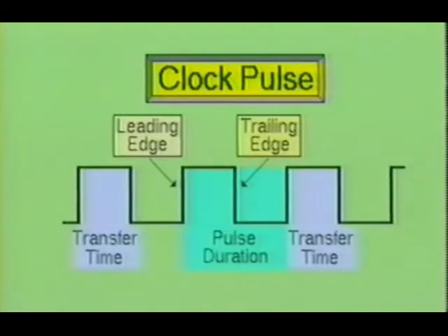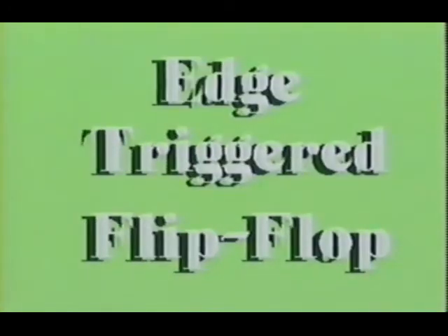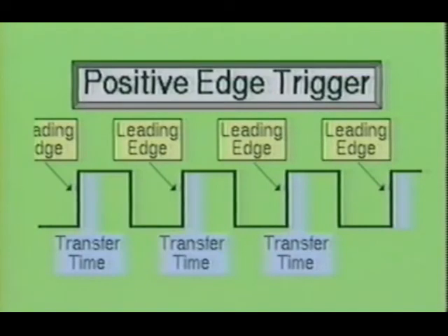In the various flip-flops shown thus far, the control inputs are effective during the interval that starts at the leading edge of each clock pulse and ends at the trailing edge of the clock pulse. However, there are times when the inputs must only be effective for a short interval of the clock pulse duration. In such a situation, the edge-triggered flip-flop satisfies this need. In the positive edge-triggered flip-flop, the control input is sensitive for a short interval of time near the positive going transition of the clock pulse. The outputs of the flip-flop change shortly after this interval.